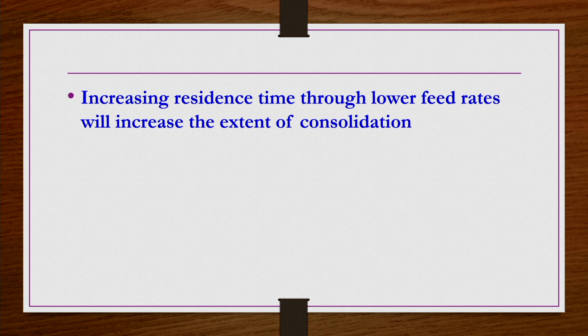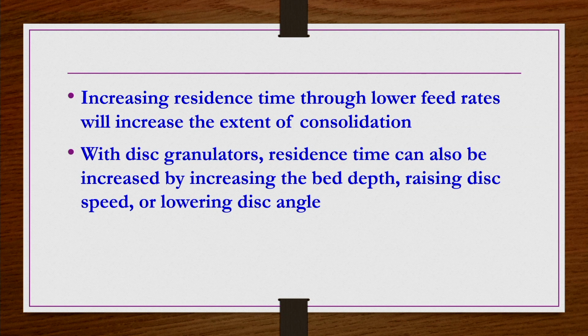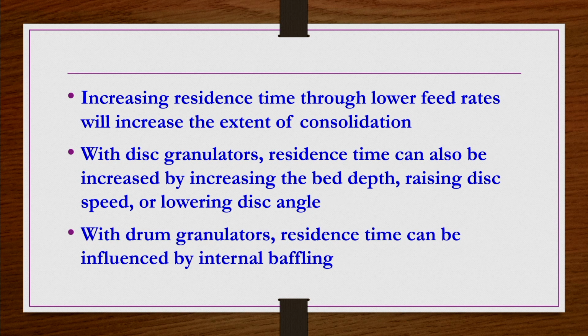Further, increasing time through lower feed rates will increase the extent of consolidation. In the case of disc granulators, residence time can also be increased by increasing the bed depth, raising the disc speed or lowering the disc angle. In the case of drum granulators, residence time can be influenced by internal baffling.